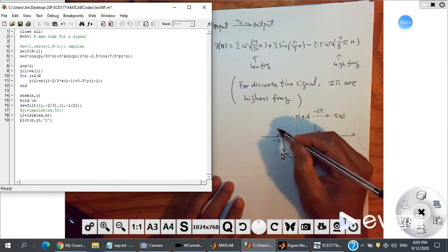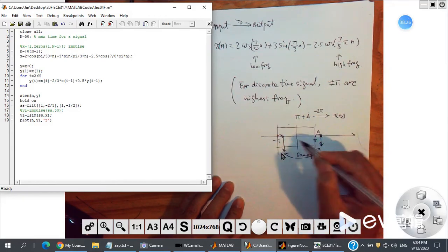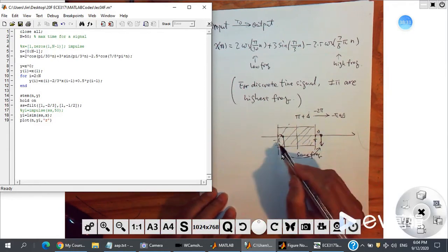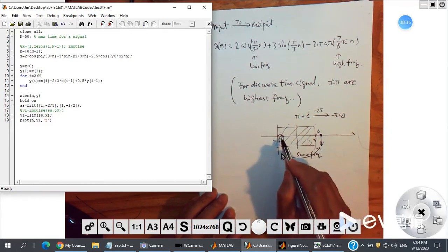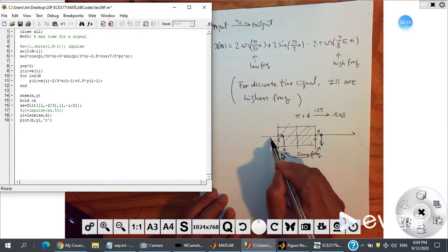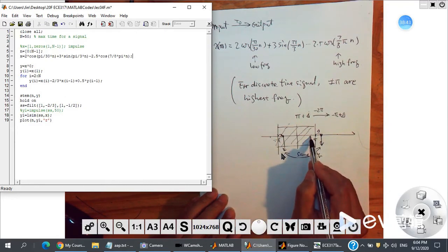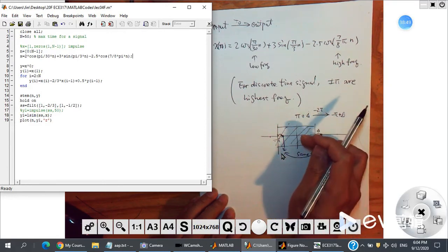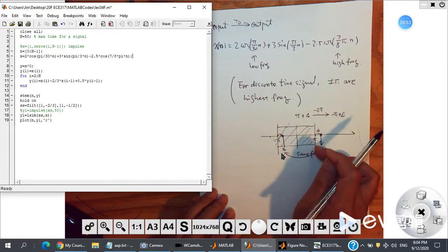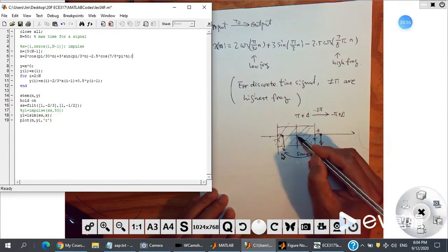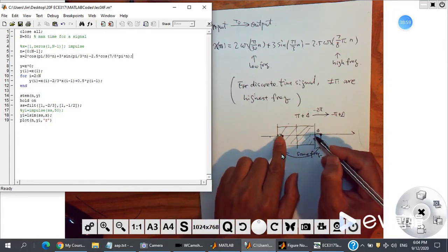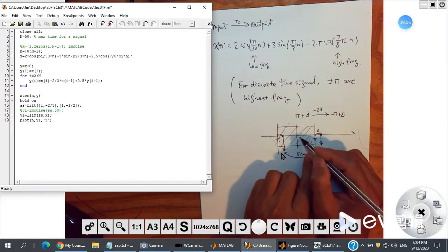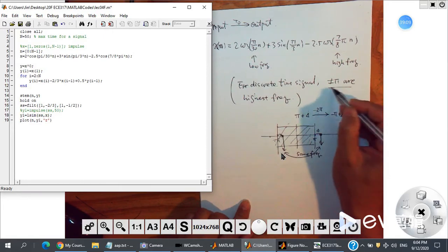And we use the value between negative pi to positive pi as the main interval of the frequency, just negative pi to pi. Over pi, it will go back to here. And the other side is the same. If frequency is here, you plus pi, you will go to here. So any frequency you plus or minus some 2 pi's, that frequency will finally go to inside this interval negative to positive pi. 0, of course, is the low frequency, right? Then going up to pi, that is highest. Then it will go back. If you go outside, it will go back. So the high frequency is just near positive and negative pi.